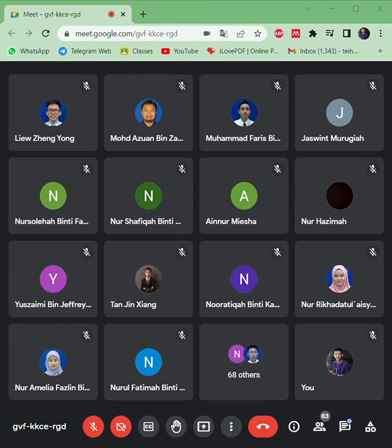But normally, if you find a catalog of material, for example glass, in terms of building specification, normally we use the term U value. What is the U value of the wall? What is the U value of the door? What is the U value of the windows? Okay. So normally we want to use U, but to get the U value, we need to find the R value first. Okay, then we look back at this question.